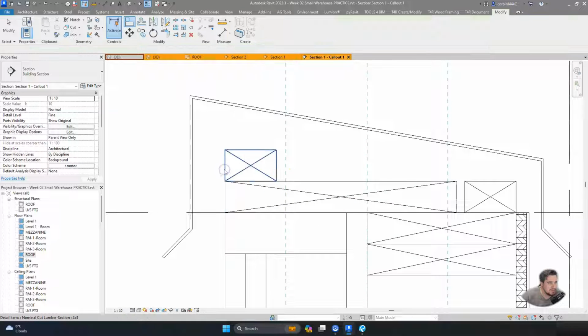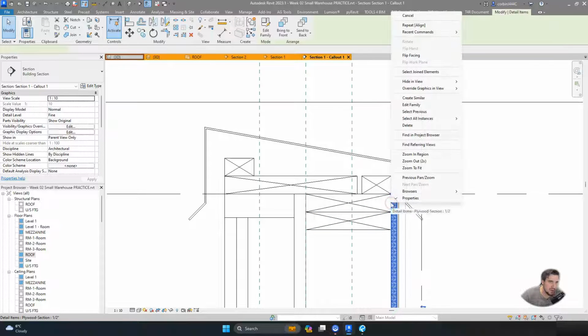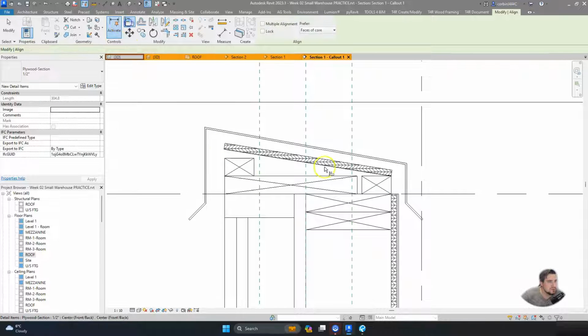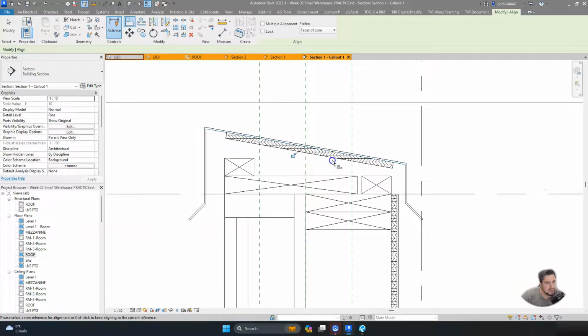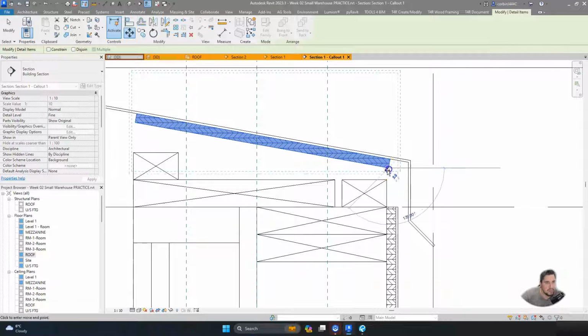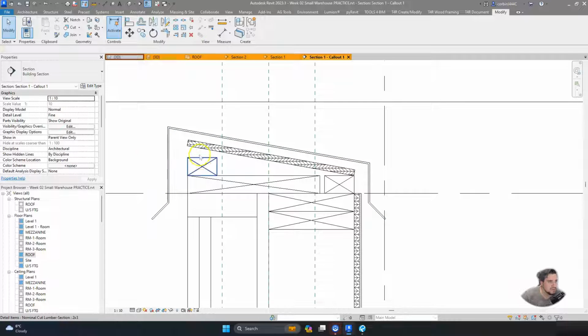And I'm just going to align these on the corners. And what we're going to do is click on this sheeting. This is kind of a little speed trick that I use. I'm going to right click, go to create similar. And now we can bring this piece of plywood in here. Sometimes what I'll do too, when I have something that's sloped like this, I'll just align it and then drop it back down. And that way, again, saves time and efficiency with doing this.